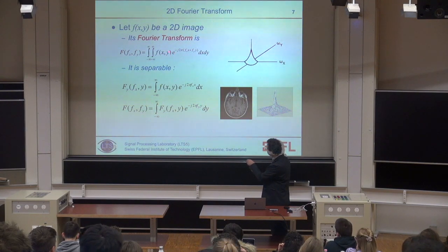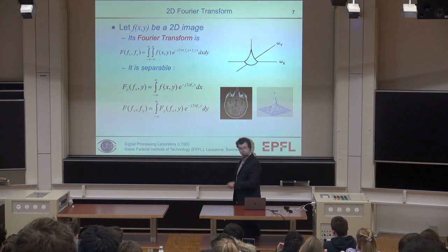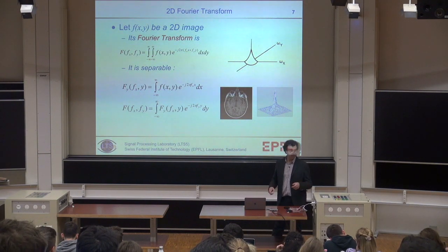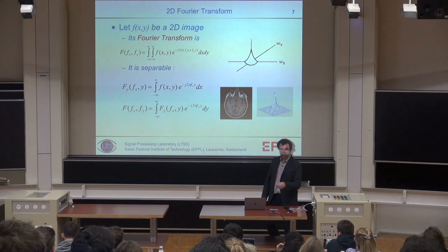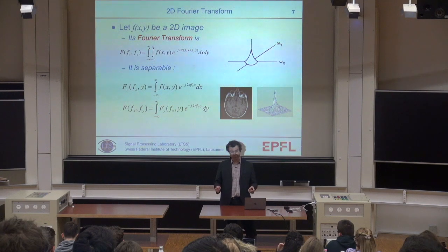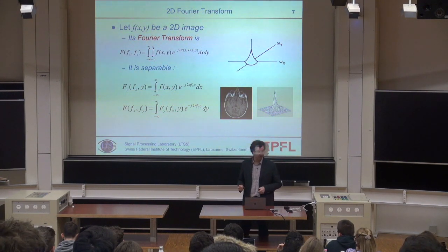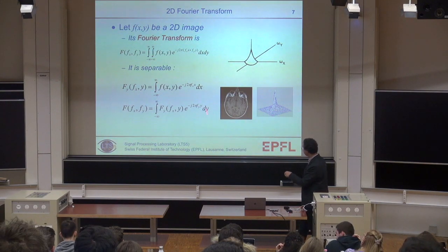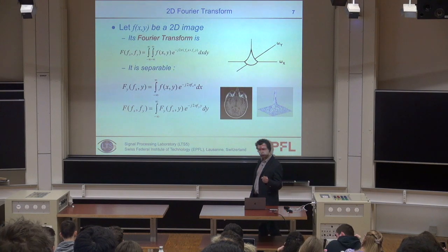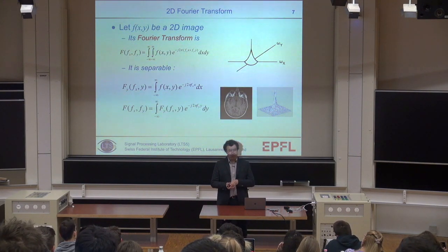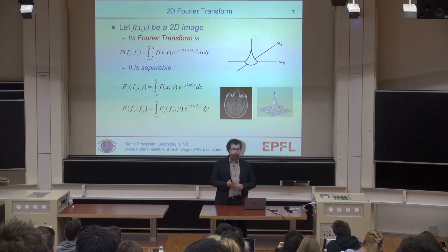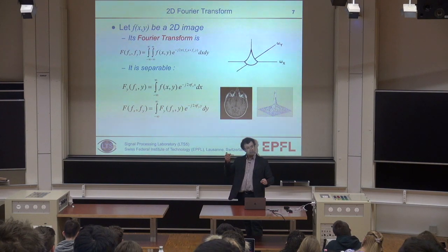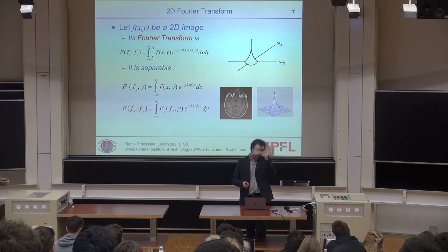But it's pretty much the same. You convert a 2D image, which is that, into another 2D signal, which is the frequency content of my image. What is the frequency of an image? We have to think a little bit about that. But in terms of math, it's exactly the same. I have 2D spatial coordinates, and I will convert them into 2D frequency, spatial frequencies. Might not be that trivial. But at the end, from an image, you get the spectrum of the image in 2D. So if your image is that, you get a 2D spectrum. What does it code? It codes the frequency content of your image. It codes whether you have very shaky pixels, so one pixel black, white, black, black, black, white, black, black, or if you have very smooth images, whether you have noise, which is most probably in the high frequencies, whether you have stripes, whether you have something.